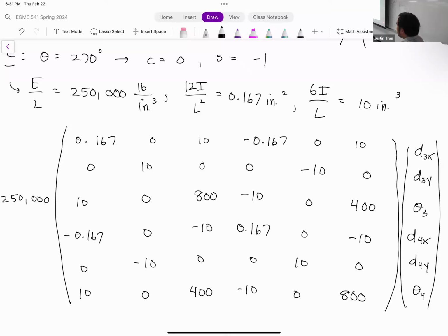So just writing the element stiffness matrices for these is a doozy, right? And even though you may talk about it and say like a standard beam by itself is a 4x4 element stiffness matrix, a 2D truss is 4x4. A 4x4 element stiffness matrix is only 16 entries you have to write down, right? Upgrading to a 6x6 is 36 entries. And so it grows literally exponentially. And so, definitely don't underestimate these problems and take them slow because they can definitely take a lot to do.